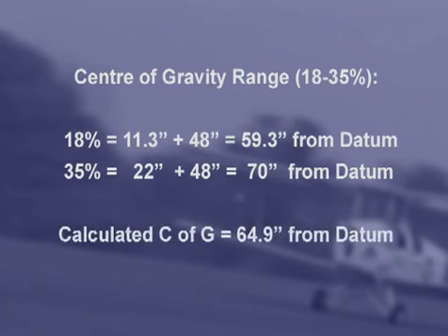64.9. So are we good? Your center of gravity is good, and your gross weight is good, and I am actually quite amazed because you've loaded this airplane up pretty good. You got 40 pounds of baggage, you got 2 standard Canadians in there, male and female, and you got full fuel, and you're under gross and you're within center of gravity. This is a good airplane.